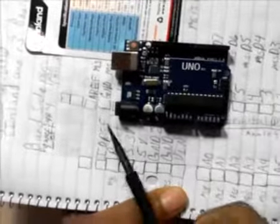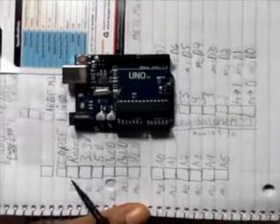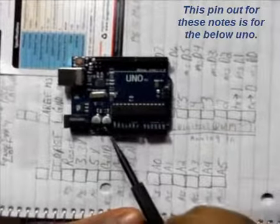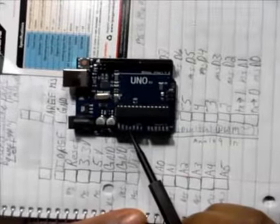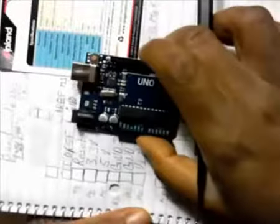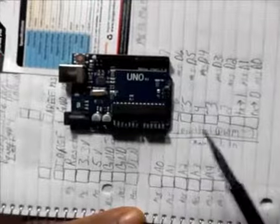Then you go to the I/O reference, and that's the very first one that you see across from this second one, and it has the title down there. And it goes down to reset. This is 3.3 volts. That's 1, 2, 3, 4 pins down. So we have 1, 2, 3, 4. That's 3.3 volts. This is 5 volts. Then you have 2 grounds. Then your VIN. Then you go into your pins. That's your analogs: A0, A1, A2, A3, A4, A5.